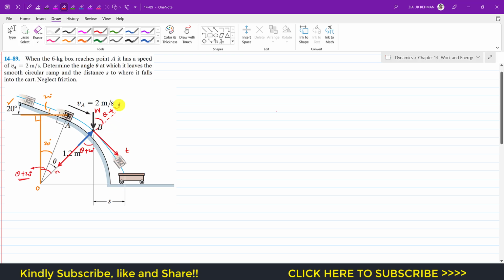Now if we resolve this weight, this weight will have one component in this direction, towards the positive normal direction, and this will be weight cos of theta plus 20 degrees. Now if we apply the summation of forces along the normal direction, that will be equal to m an, and as we know that an is always equal to the velocity squared divided by rho. And if we are applying at some arbitrary position point B, this will be VB squared.